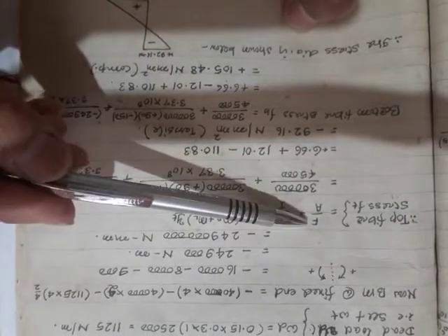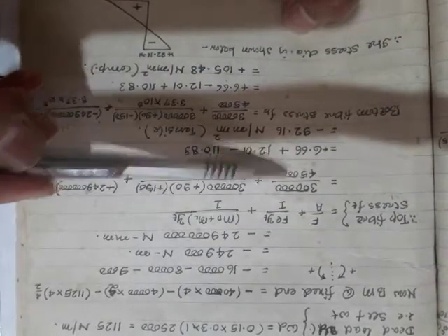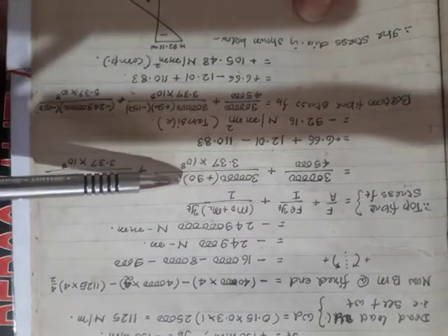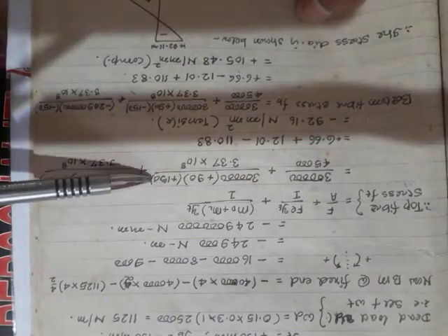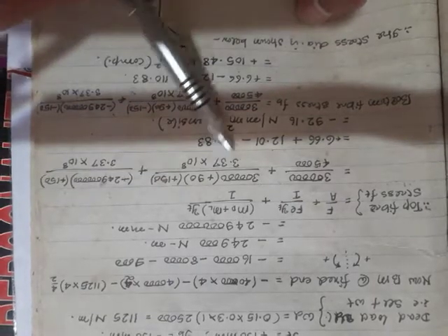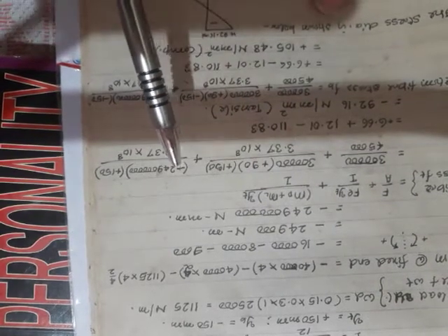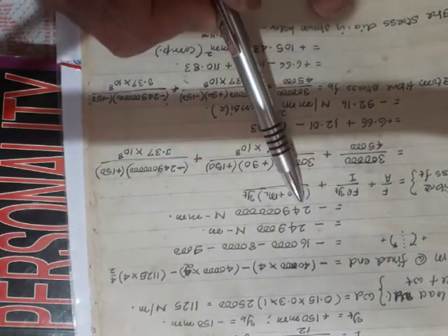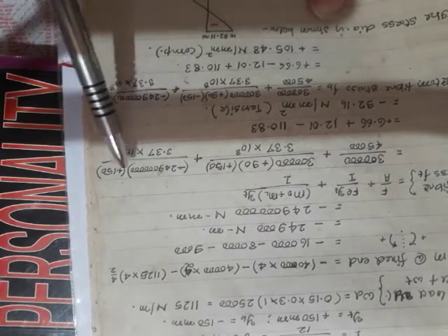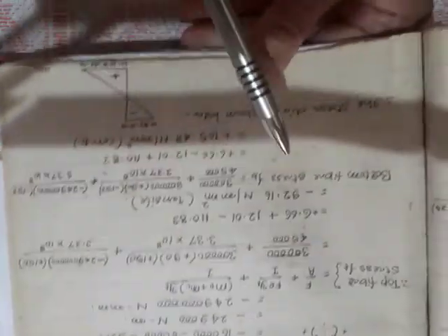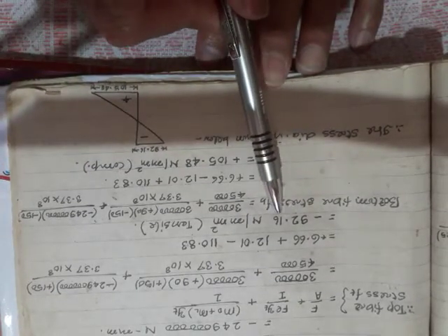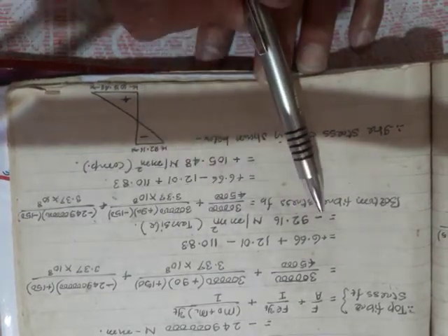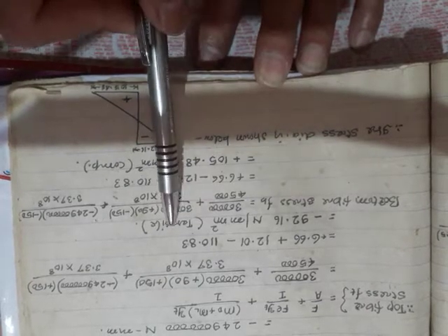F, the prestressing force, and area you know; eccentricity is plus 90; YT, since it is above the CGC, is plus 150; moment of inertia you know; and bending moment M is minus, because it is a cantilever. You can easily calculate the value as minus 92.16 Newton per mm square. The minus sign indicates that it is tension.